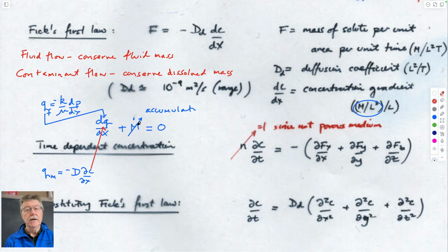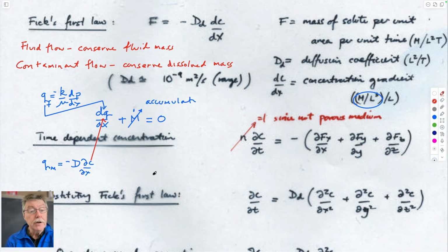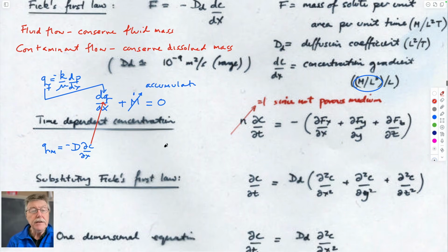That's all it is. So control volumes are kind of important to us. That's why we talked to you about them early in your career. So if you substitute this into here, you get a relationship that says, instead of being defined in terms of, this would be dP, this ends up being d2P dx squared equals, it's not specific storage, it's equal to some compressibility dP dt.